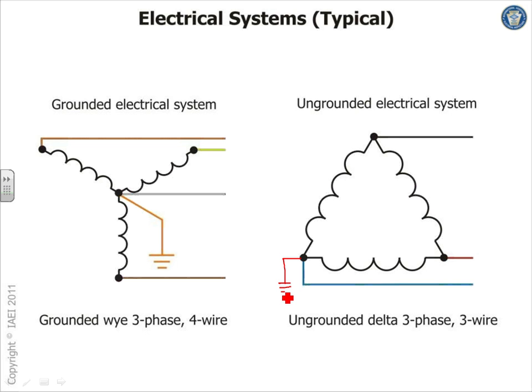Right? What's the voltage to ground? And this system happened to be 480. If you have a delta ungrounded and you have a ground fault in one phase, what happened? Nothing will happen. But you have a ground, one phase grounded. The system continued to work. Now what's the voltage to ground now? 480. So imagine you're in a panel, you're working on a panel, and I read an article, guys.